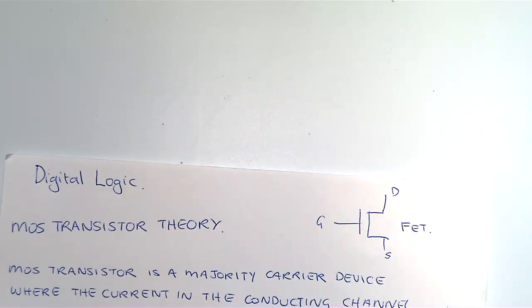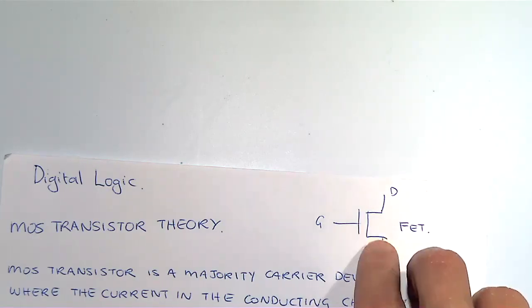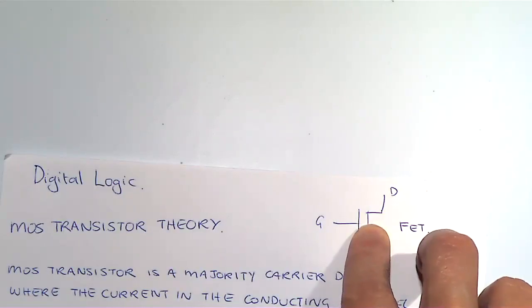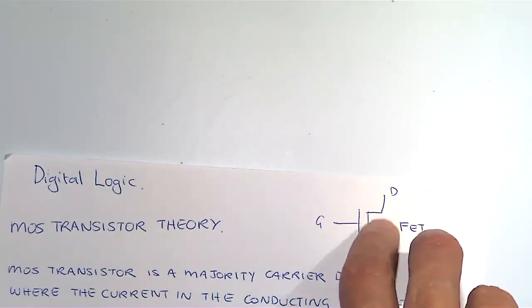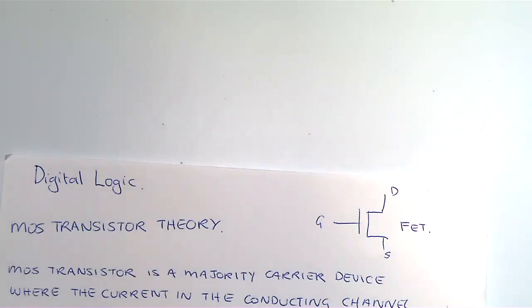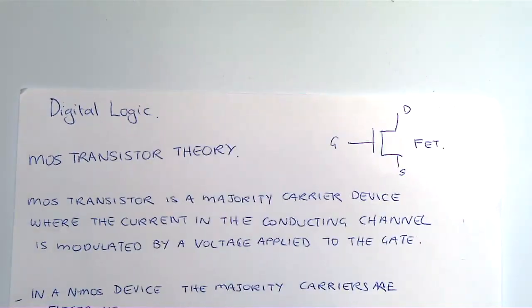Well, it's used to signify the type, that's right, and it's not actually used to signify if it's PMOS or NMOS. It's used to signify if it's enhancement or depletion, but usually what you're doing is tying something to the substrate. So really, when you're looking at a FET, it is actually a 4-terminal device that you need to consider.